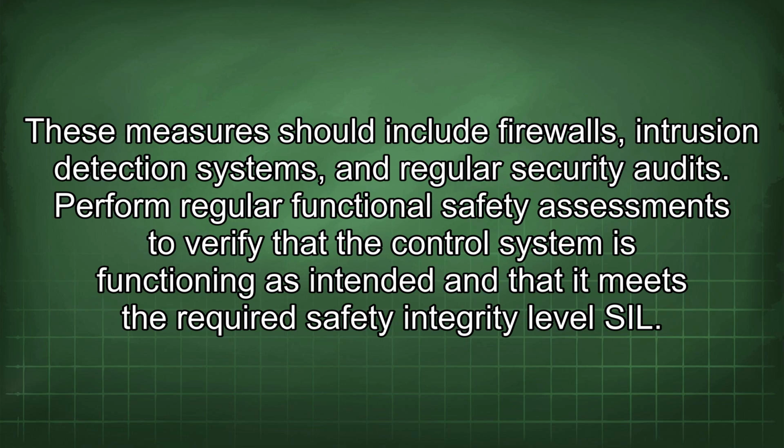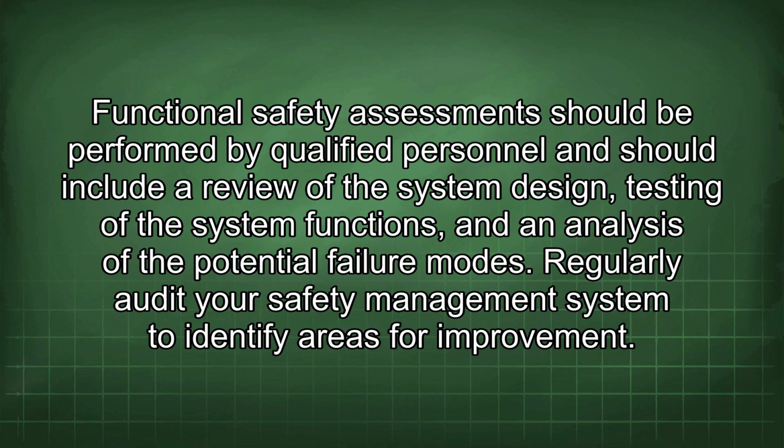Perform regular functional safety assessments to verify that the control system is functioning as intended and that it meets the required safety integrity level (SIL). Functional safety assessment should be performed by qualified personnel and should include a review of the system design, testing of the system functions, and an analysis of the potential failure modes.